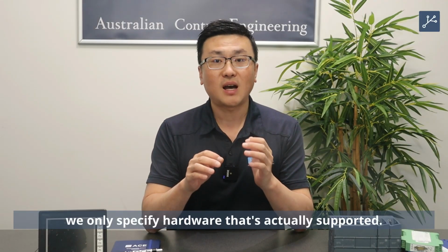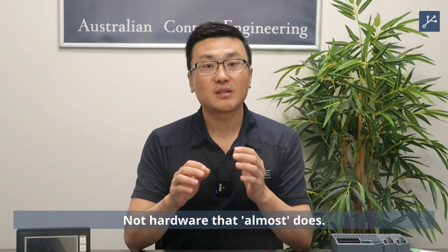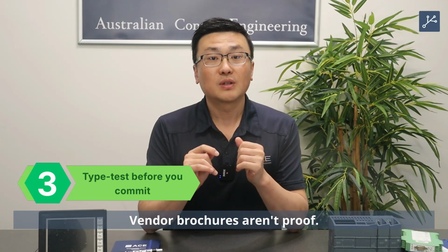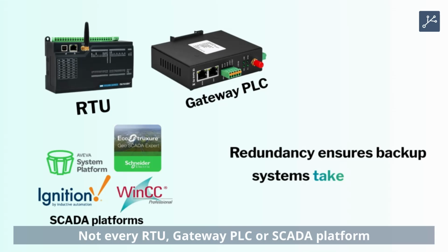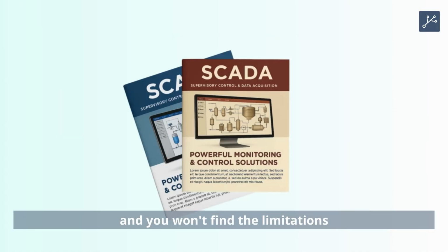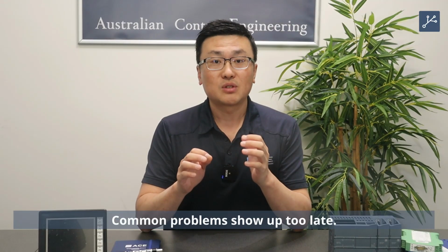only specify hardware that's actually supported, not hardware that almost does. Vendor brochures are not proof. Not every RTU, gateway, PLC, or SCADA platform supports every redundancy mode, and you won't find the limitations in the marketing material. Common problems show up too late.